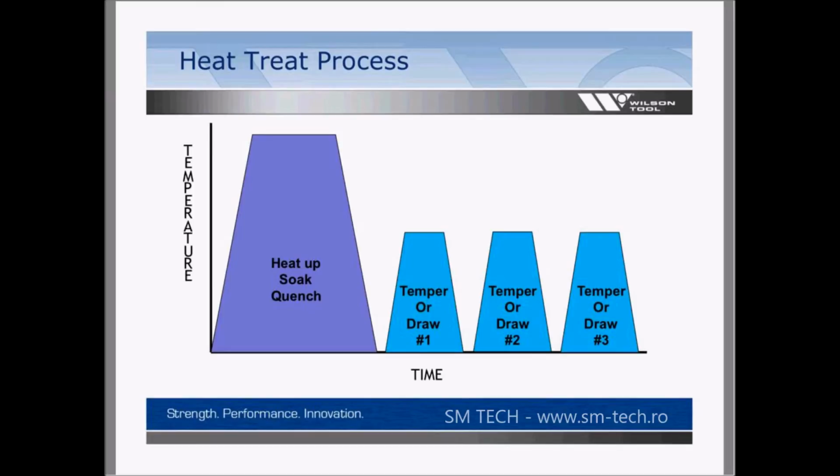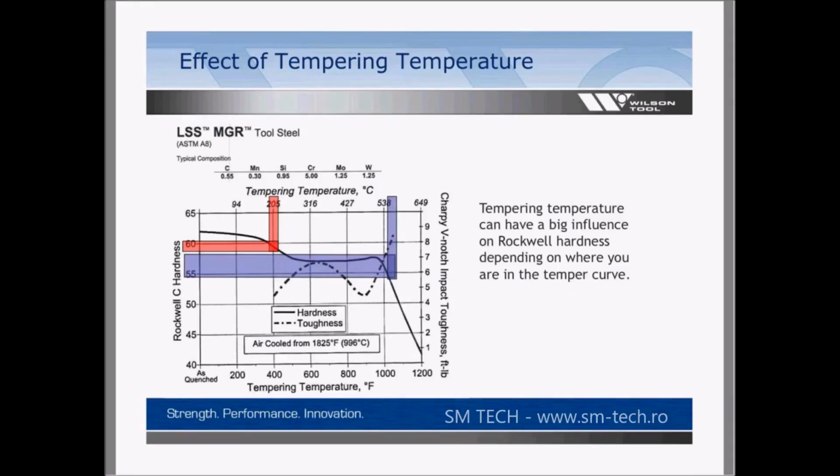So you've got to vary different temperatures, and you want to make sure your tool steel providers, or if you're doing this in-house and sending it out, that your metal treaters are working towards optimal performance and not batching this with a bunch of other stuff. When you batch materials, you have a big effect on the process itself. Tempering is usually when you see these big changes. This here is an example of A8, where it does change pretty quickly depending on that process.